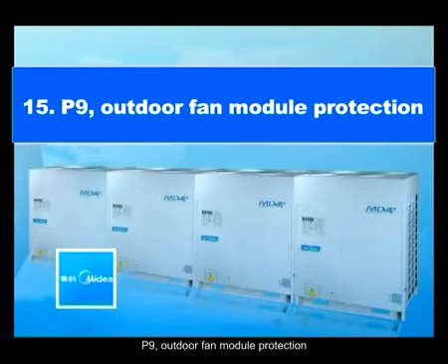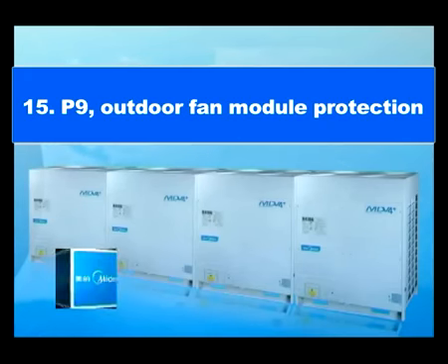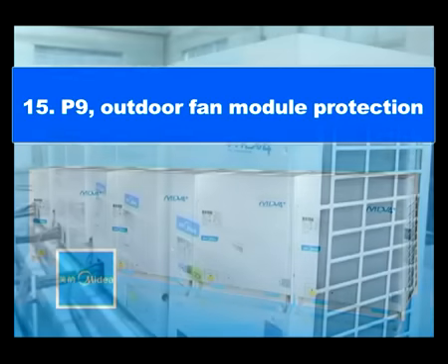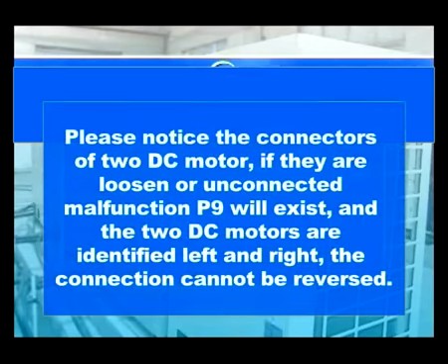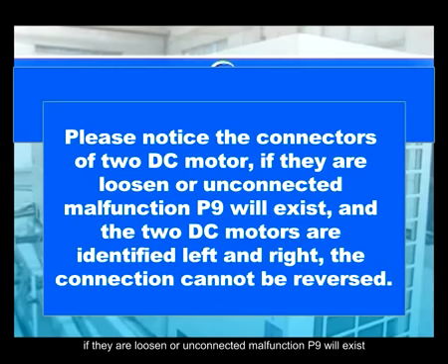P9. Outdoor fan module protection. Please note the connectors of 2 DC motor. If they are loosened or unconnected malfunction, P9 will exist, and the 2 DC motors are identified left and right. The connection cannot be reversed.